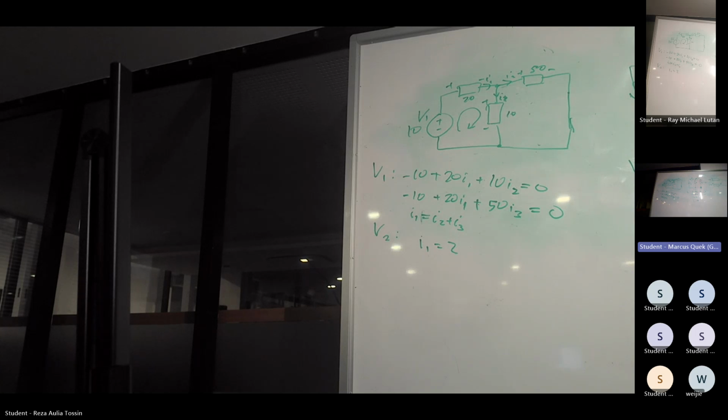You don't put the resistor, the LED in. So the minus of the diode is shorted to ground, correct? Yeah. And the other one is to the battery. So there's a reason why we have a resistor in series with LEDs. Because you just short the battery.